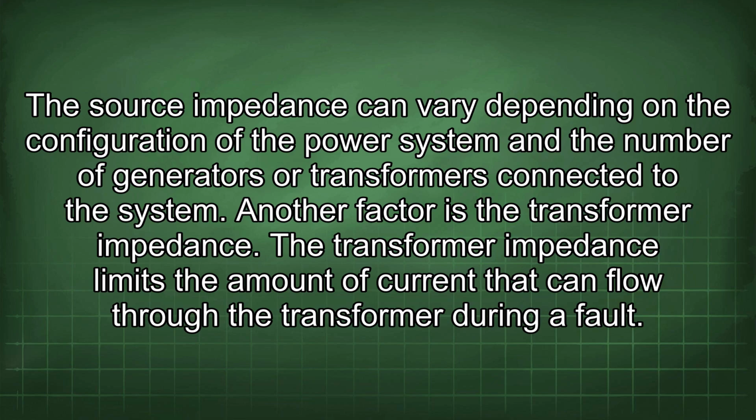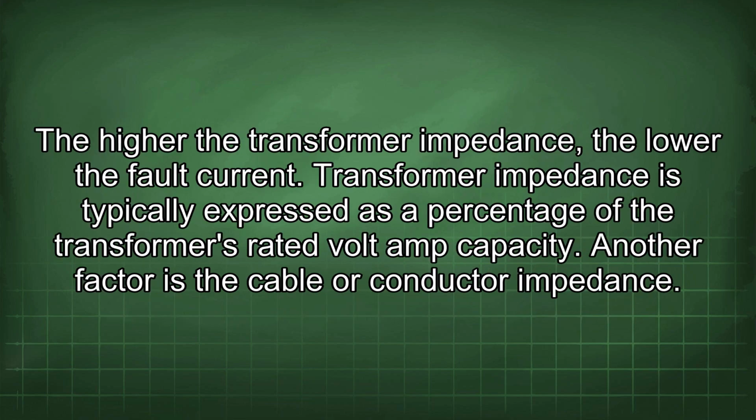Another factor is the transformer impedance. The transformer impedance limits the amount of current that can flow through the transformer during a fault. The higher the transformer impedance, the lower the fault current. Transformer impedance is typically expressed as a percentage of the transformer's rated volt-amp capacity.